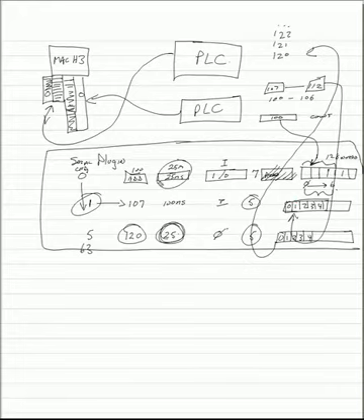The old serial ModBus, by the way, when it's sending data back and forth to Mach 3's serial buffer, has a break in the transmission called ModIO processing. In ModIO processing, if you've told Mach 3 that you're running a ModIO, it will take the first address, which is register 0, and stick it aside as an MPG value.